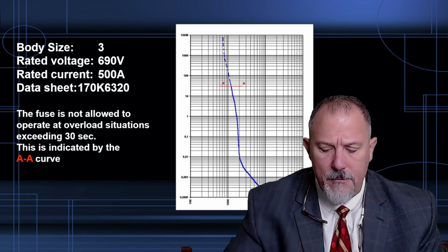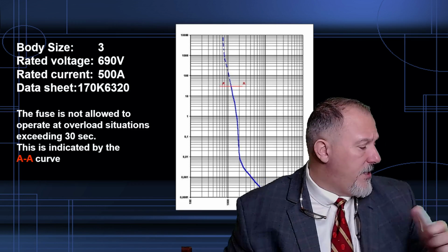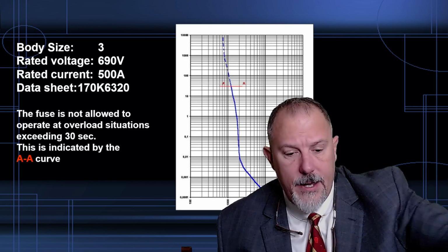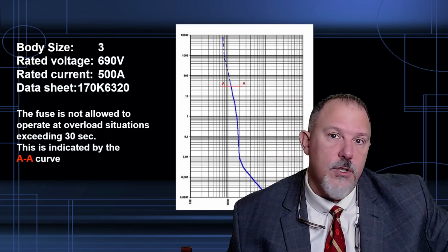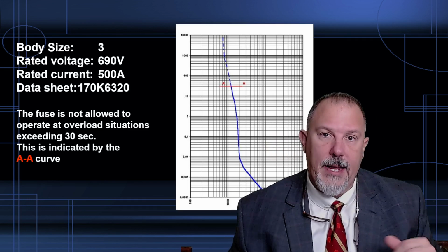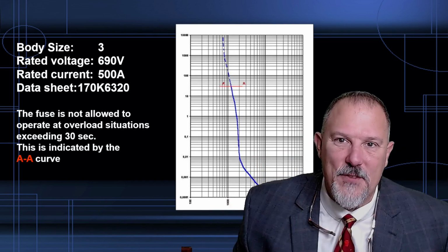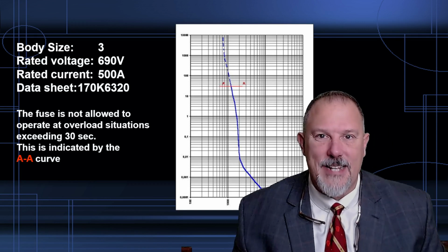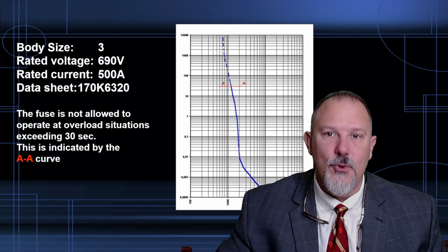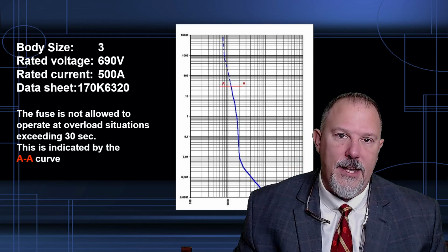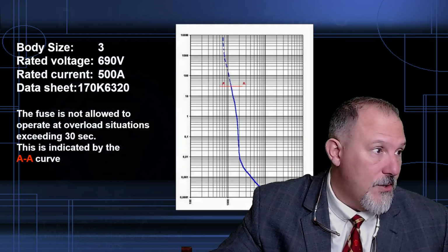I'm telling you, my first experience with sizing one of these, we had an application with an OEM who needed a replacement fuse, a high-speed fuse that was no longer made. And my brain went into, well, what's the ampere rating of the circuit? What is the conductor that you're trying to protect? And they said, no, here's how many joules I can let through. I have to be less than this much energy. And that's how you pick these fuses.